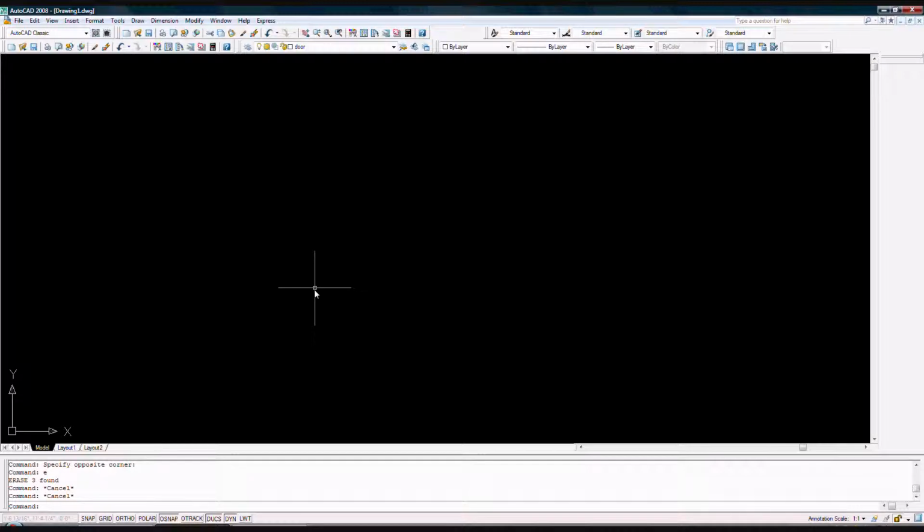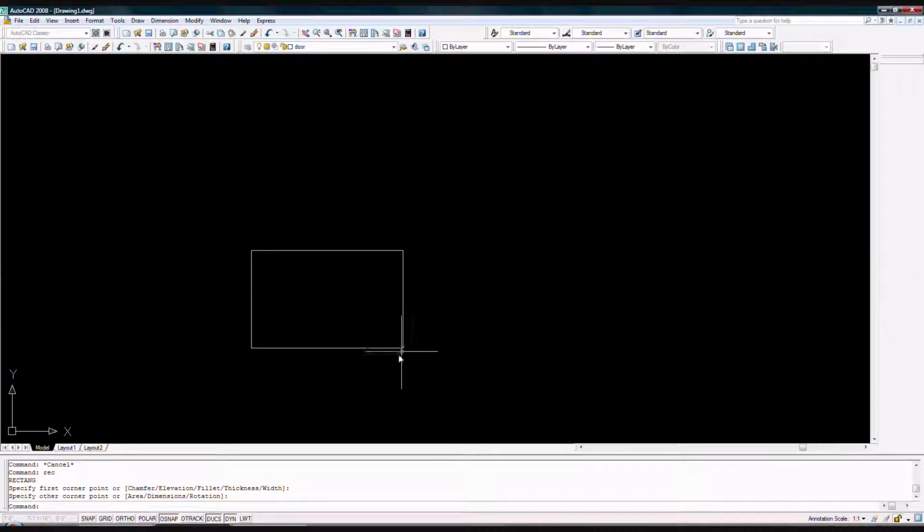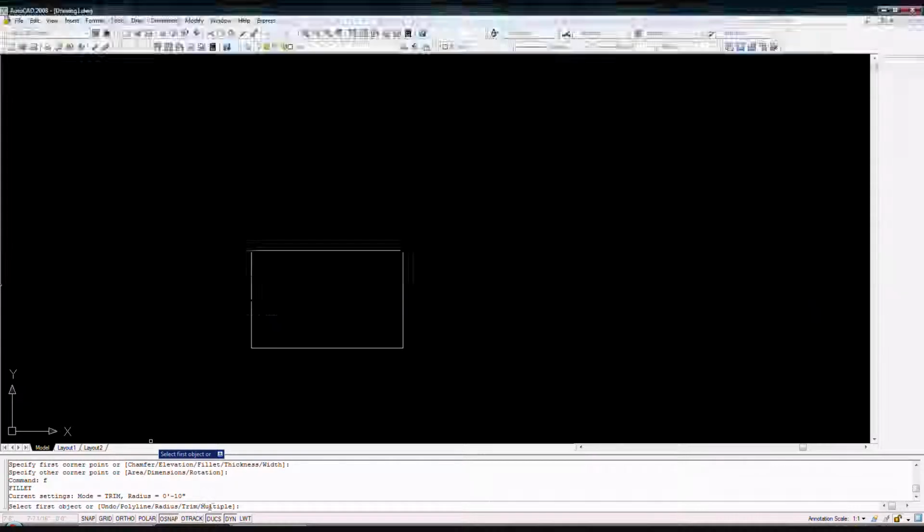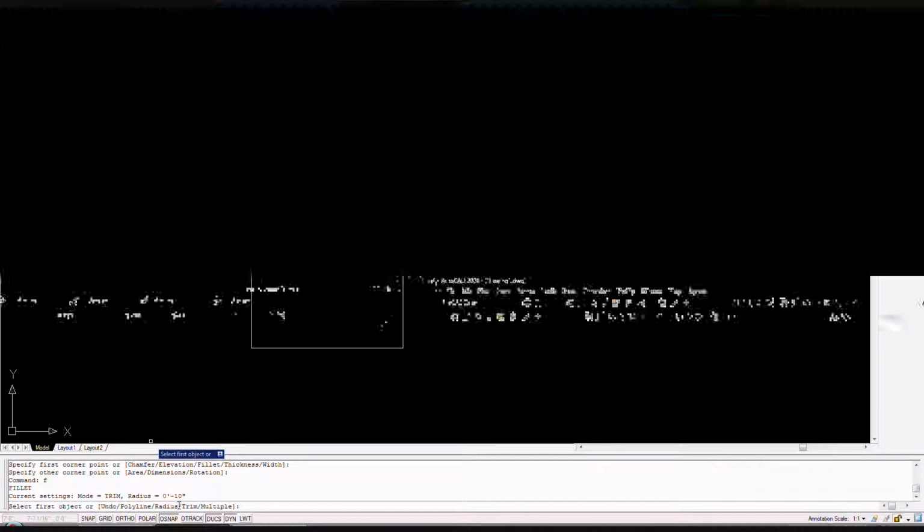And there are other options like angle and many other things which you can always apply. So the keywords to apply all those are, say, REC enter. Then say I want to fillet that, F enter. Then see all the capital letters, which are the ones you have to type in. Say polylines: the P is the capital letter, so P enter will go to the polyline.